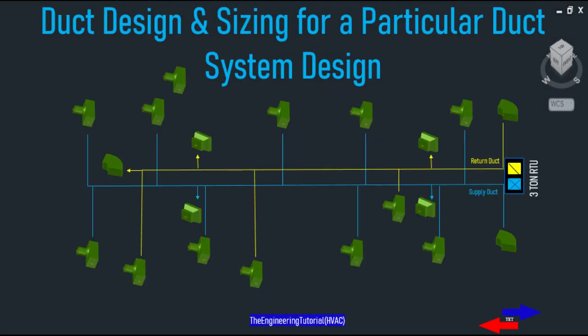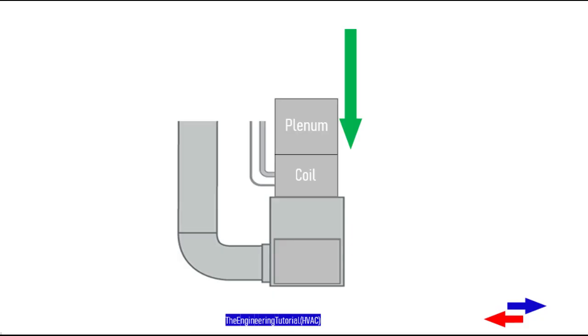And do not install a duct at the end of a plenum. That will cause too much airflow. Please install duct in the side of a plenum. A duct at the end of a plenum will receive too much airflow that will be noisy.